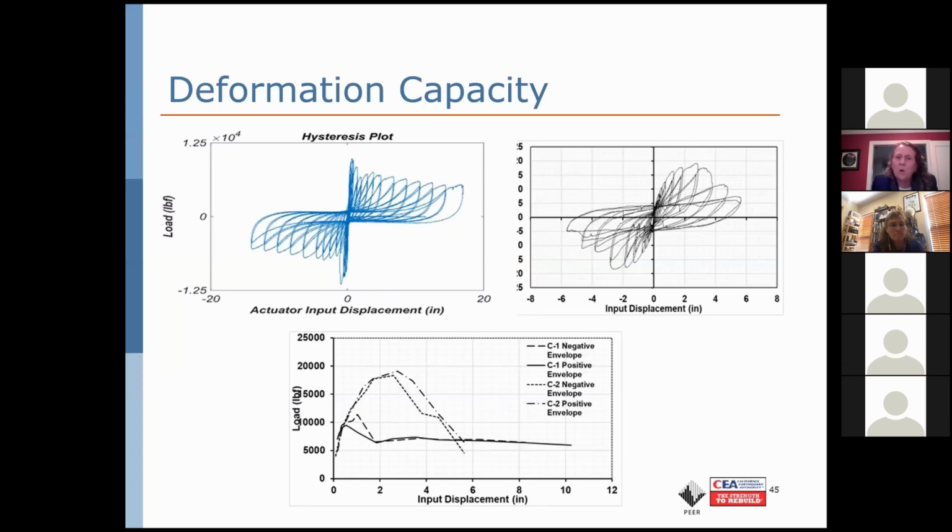One last thing I'd like to point out in terms of deformation capacity. This is specimens C1 and C2. These are our superstructures, and the one on the upper left is horizontal wood siding exterior and plaster on wood lath interior, and that amazing retention of the post-peak capacity that we see. The one on the right is C2, that was the siding and the gypboard that really failed by pulling it off the base and really was no longer a functional system at 6% drift, or maybe before that if it hadn't been restrained.